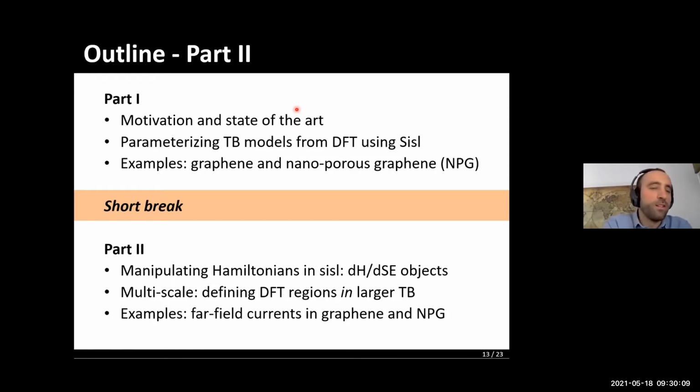For example, when you try to make a projected Hamiltonian for hBN, or for MoS2, the basis sets are different for the 2 chemical species. You have the chance there. You need to select different orbitals on different chemical species in that case. So you can do that just by applying the suborbital command sequentially.